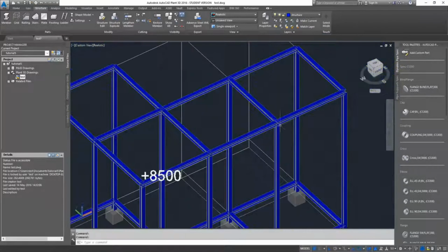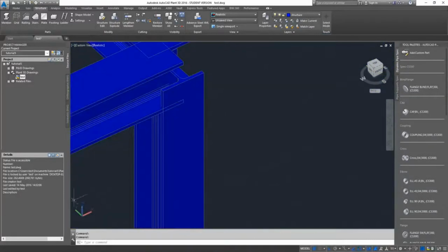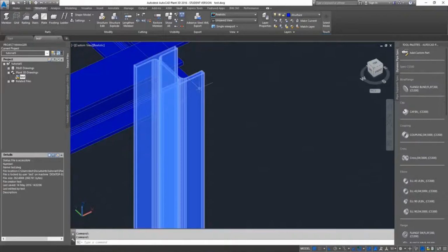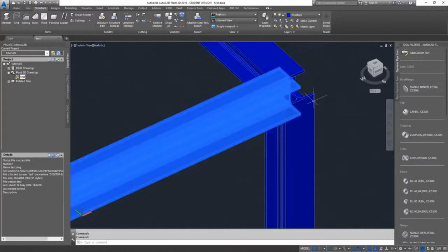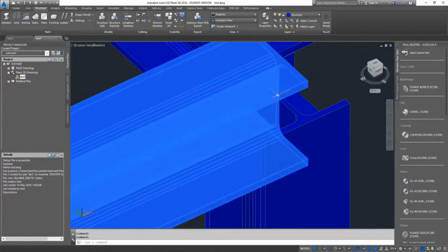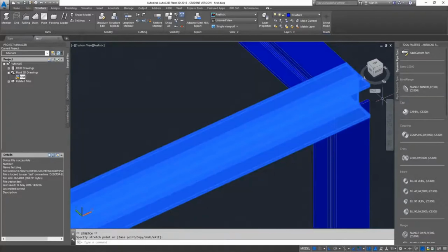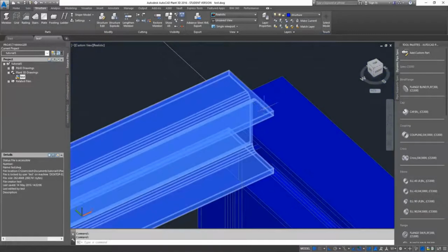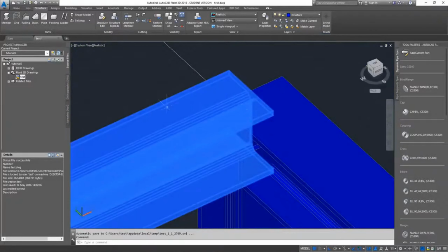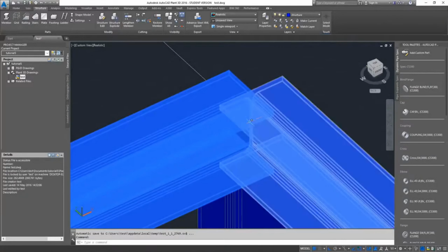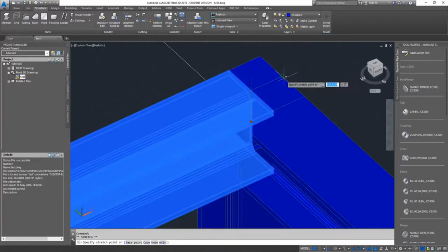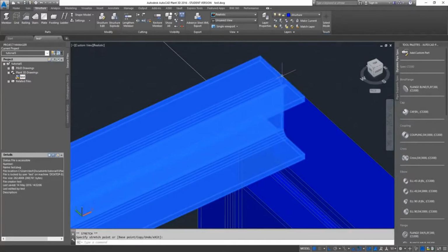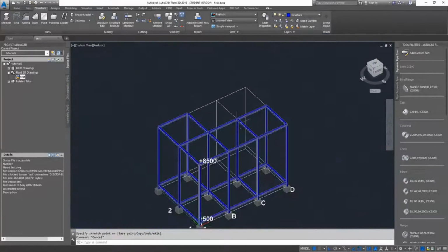We're going to do that on all these corners because it's going to help us out quite a bit. Again, it doesn't matter which way you're looking at it, you can always select that little grip, extend it and click, and it's extended. Let's look at the other point. Again, it doesn't matter what your view is, you can still select it through the 3D object. As long as this is the only thing that's selected, I should be able to just snap onto it and go to the plane that I wanted to extend it to, or any edge really.